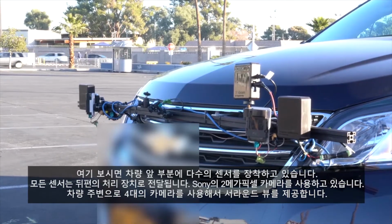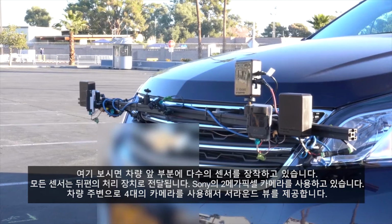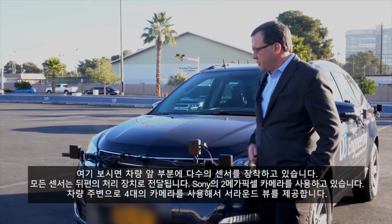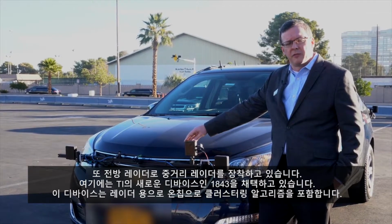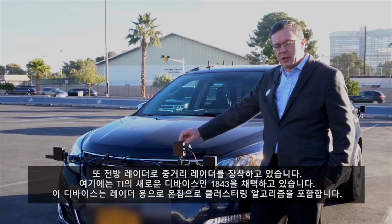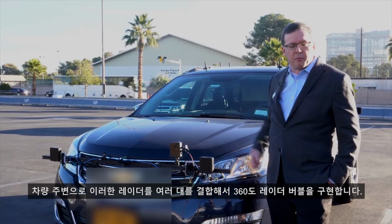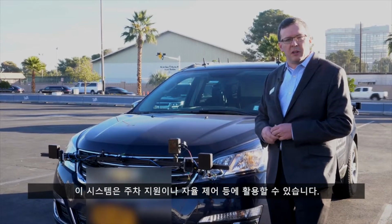So we have a handful of sensors on the front of the car here. All are fed back to the compute bed in the back of the car. This has a 2 megapixel camera from Sony that's stitched into 4 cameras like it around the car for surround view. We have a forward radar, mid-range radar, an 1843, a new device from TI. Does forward radar, does clustering algorithms all on chip. And then we have multiple radars that are stitched together to create a 360-degree radar bubble around the car. It can be used for parking, it can be used for autonomous control, and such.